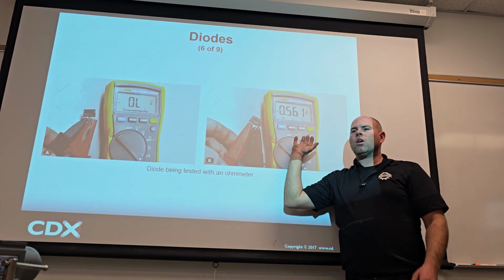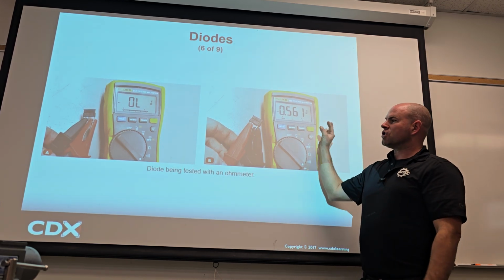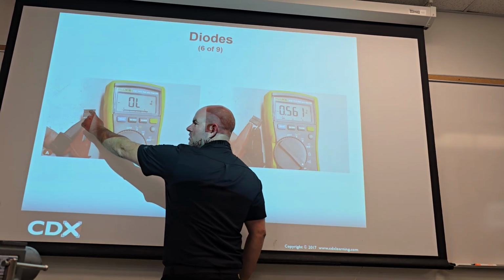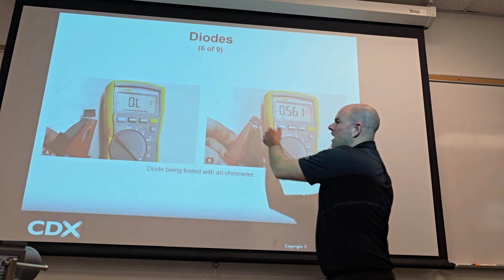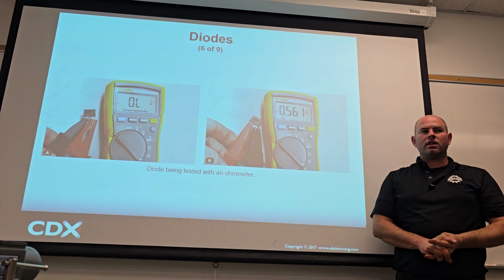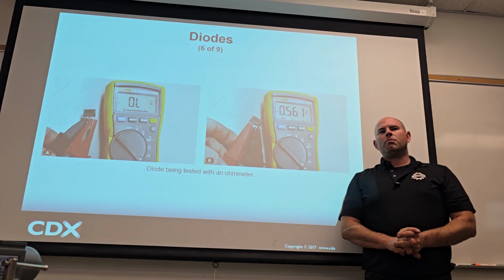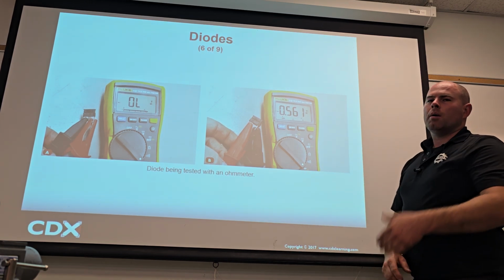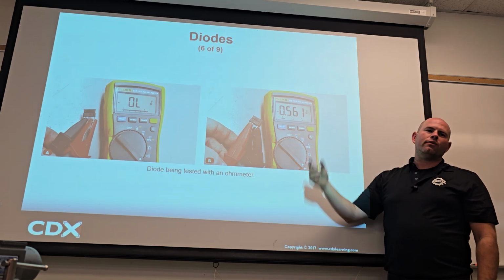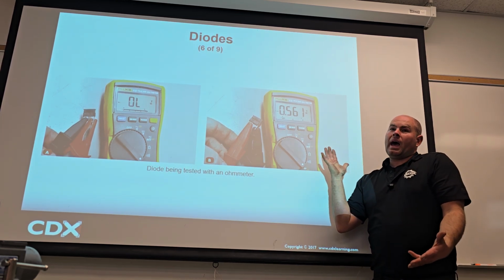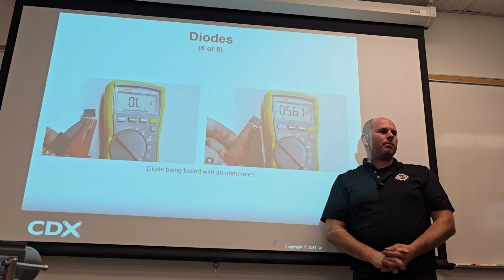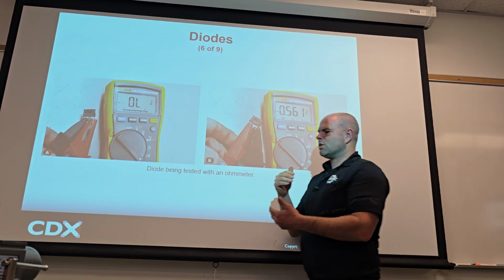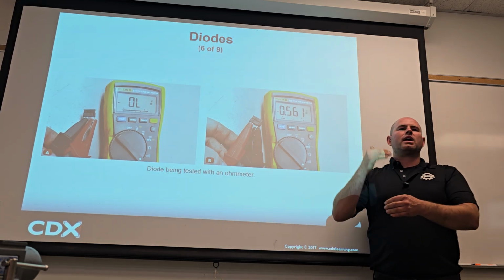Cool. So to give you a good perspective, this is a general understanding, not a case of remembering you have to have it just like this, because this is just one example. We have a lot of different diodes in a lot of different cars. You can work from memory if you want, but that's how you make mistakes. I'd look at this and say that's good, but maybe the spec was 0.250 and this one's actually bad. I would never know that from memory. I would be following the service information. The service manual is going to be critical for you to correctly fix the car.